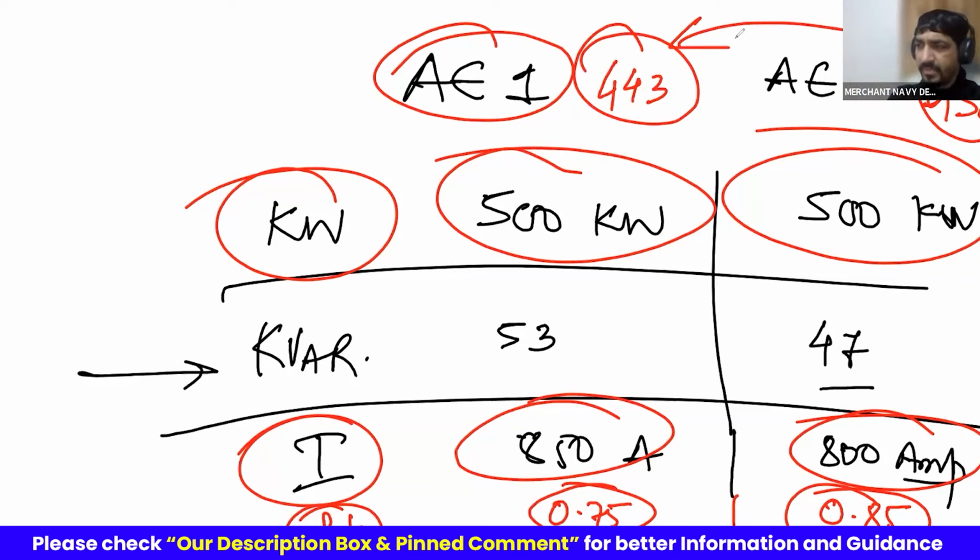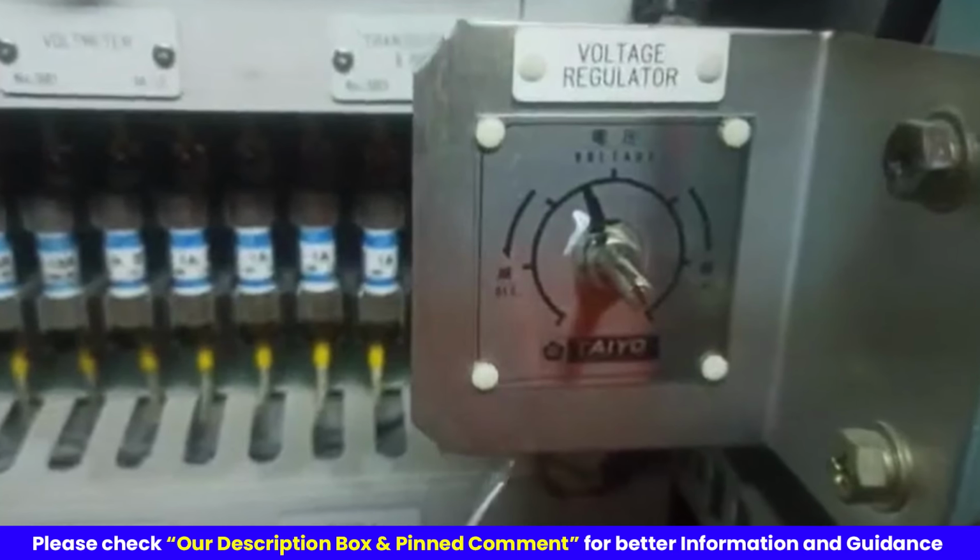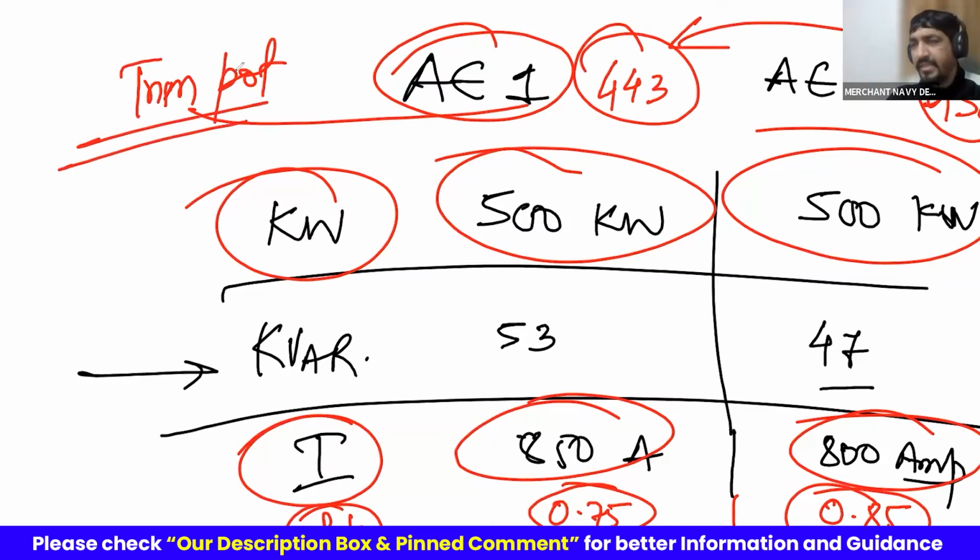In the unloaded condition, you make this 443 back to 440 again. How do you do it? There is a potentiometer given in the panel, which we call a trim pot. Open the ECR panel, the MSB panel, and make it 440 again. AE1 440, AE2 440, and once they're both 440, then you're sure that when they run, they will maintain that.